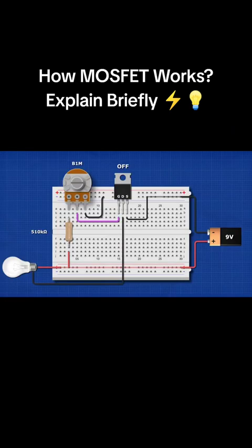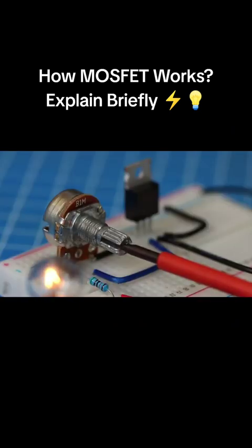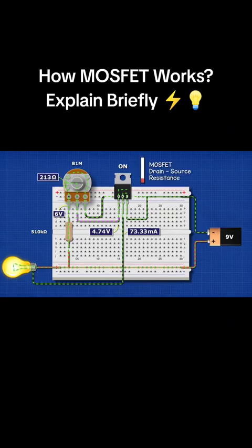The MOSFET will be activated, so the lamp turns on. The resistance is so high here that almost no current flows through the resistor. We just get a voltage. When we disconnect the power to the resistor, the MOSFET drains through the potentiometer. If we apply the voltage again, we can rotate the potentiometer to increase the resistance. That reduces the voltage available at the gate.